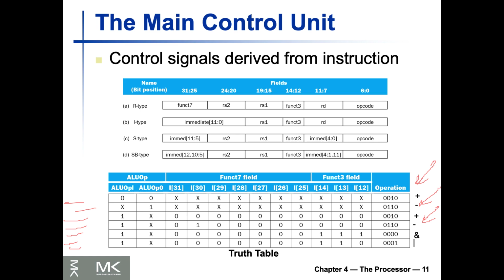For example, the ALU op does not use the encoding 11. You see, we have either 1x or 00 or x1. So instead we have, right, this or 01? We don't have 11 here. Thus, we only need these 4 func field bits as input for ALU control instead of 6. Okay, does that make sense? Because for some of them, some of the lines were not necessary, right?